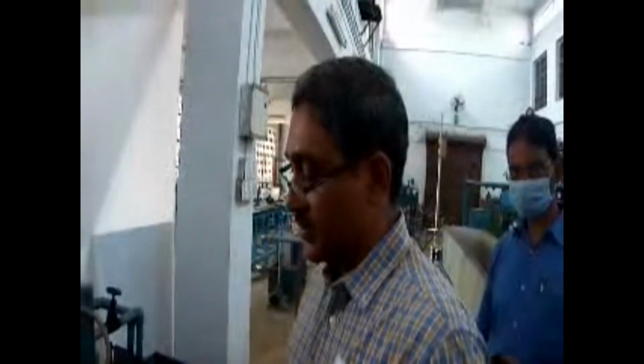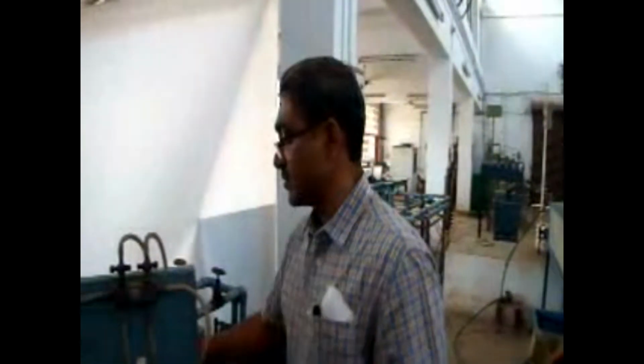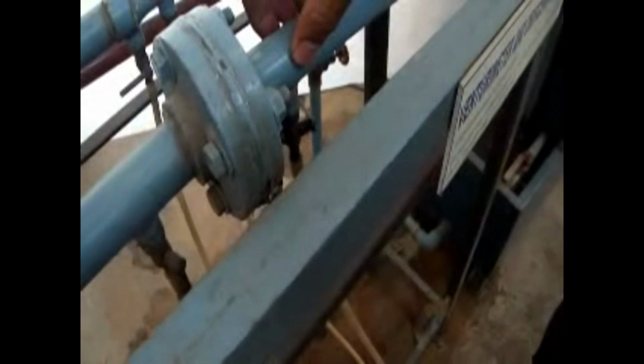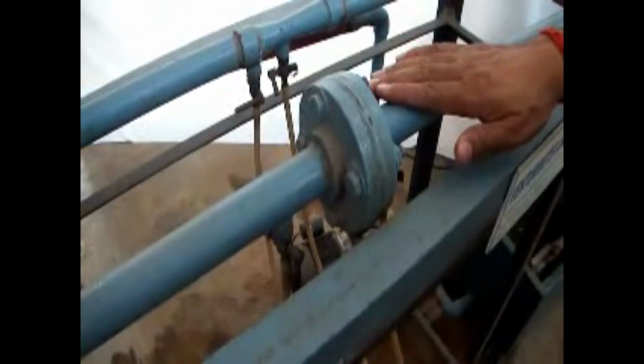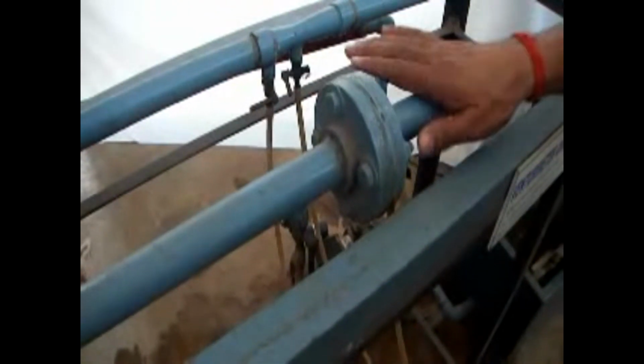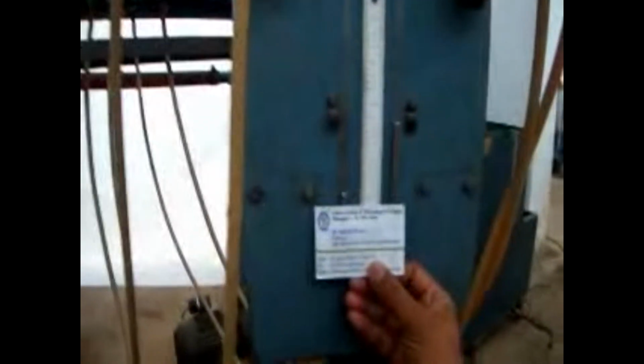So now we have connected this Orificemeter, which is supplying water from the inflow side as well as the outflow side to this U-tube manometer, and it is now a stabilized discharge condition, the supply of water is almost constant. So let us measure the head difference for this discharge condition first, and after that we will measure what the discharge is. So head at supply side it is